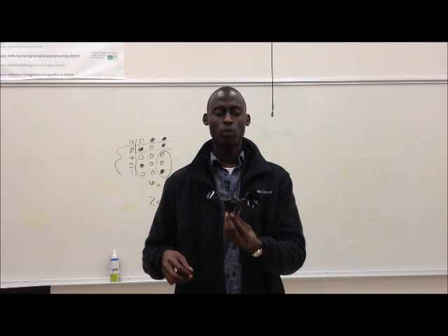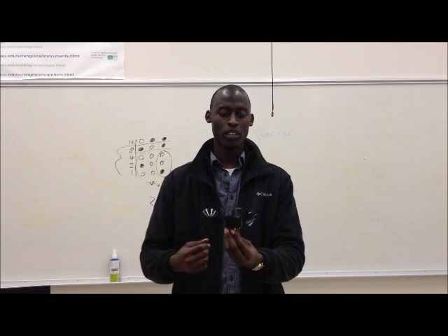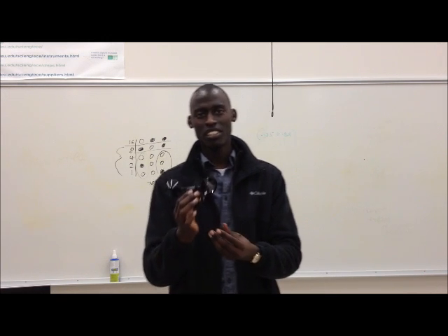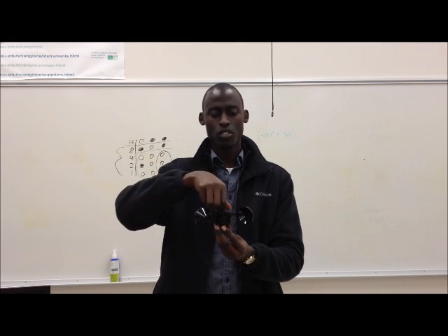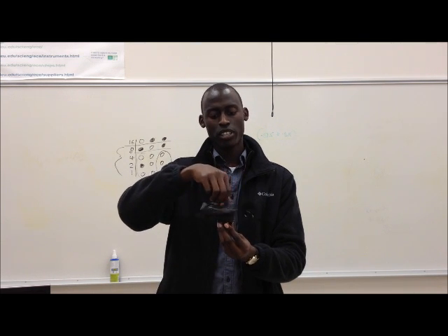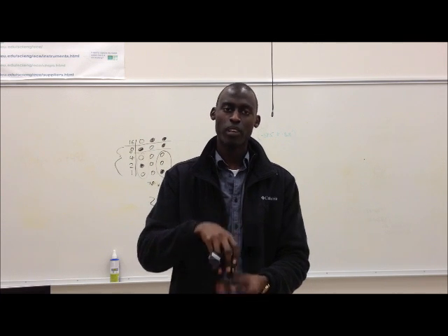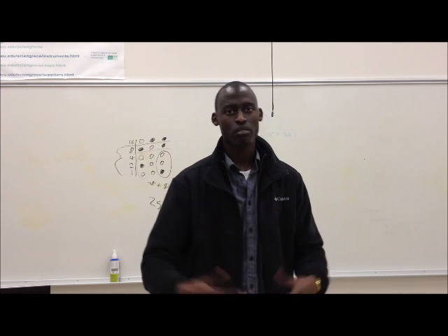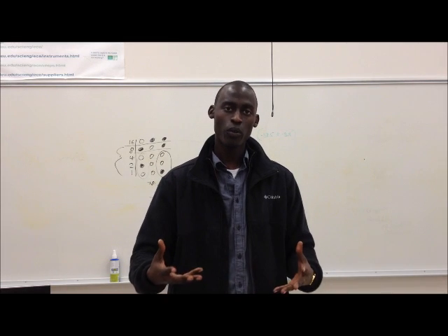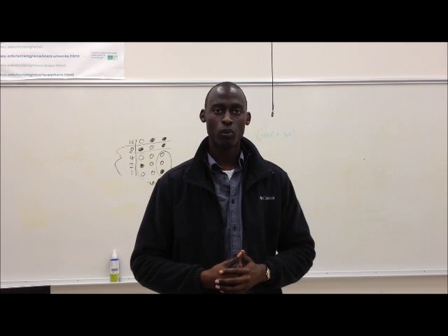This is the cup anemometer that we'll be using for the experiment. The rotation is caused by the wind. Inside this is a switch that turns the signal on and off. So when we feed power into this, the speed of the wind causes it to rotate, and the switch inside turns power on and off, and from that we get a wave whose frequency we can read and use to compute the speed of the wind.